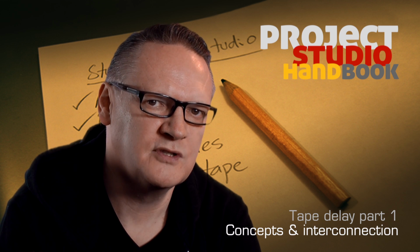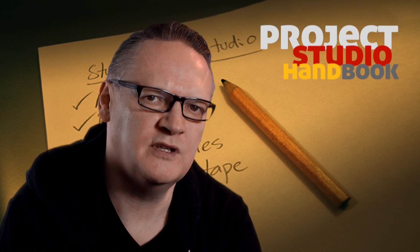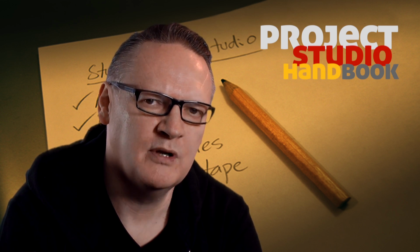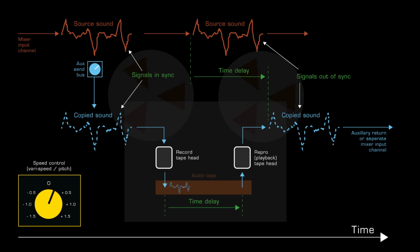Time domain effects were first made possible when sound engineers discovered they could exploit the gap between the record and repro heads of a tape recorder to delay a signal and use the speed control to modulate the delay time and the pitch. Today, the 5 primary parameters of time domain effects still derive their names from these processes.